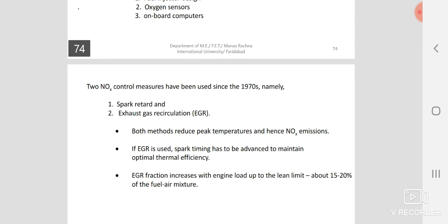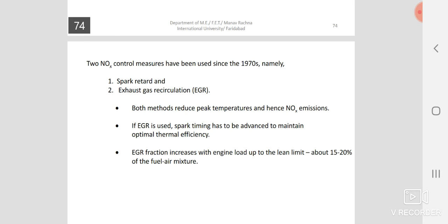When you make the exhaust gas recirculated, as a result of that, the temperature remains high. So the intensity of spark to be produced, or intensity of compression ignition to be produced, becomes less, because the fuel itself is in a higher temperature condition.